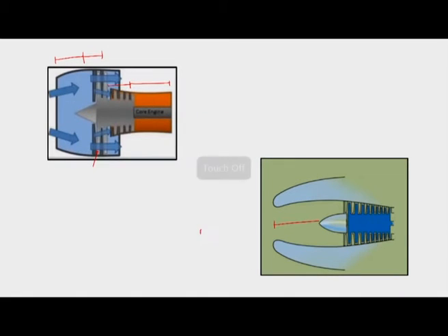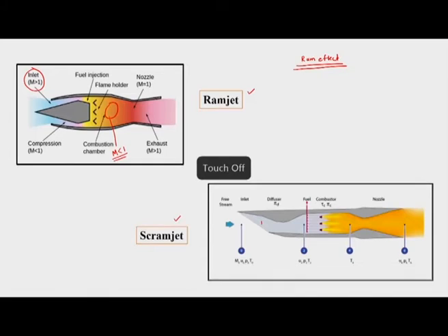is less than 1 at the inlet. Since Mach number is less than 1, we can see a diverging passage is designed as the intake. We know that in the case of incompressible or subsonic flow, an area increase is treated as a diffuser. So, this is a diffuser. The intake acts as a diffuser where we have a diverging passage, and that diverging passage raises the pressure.